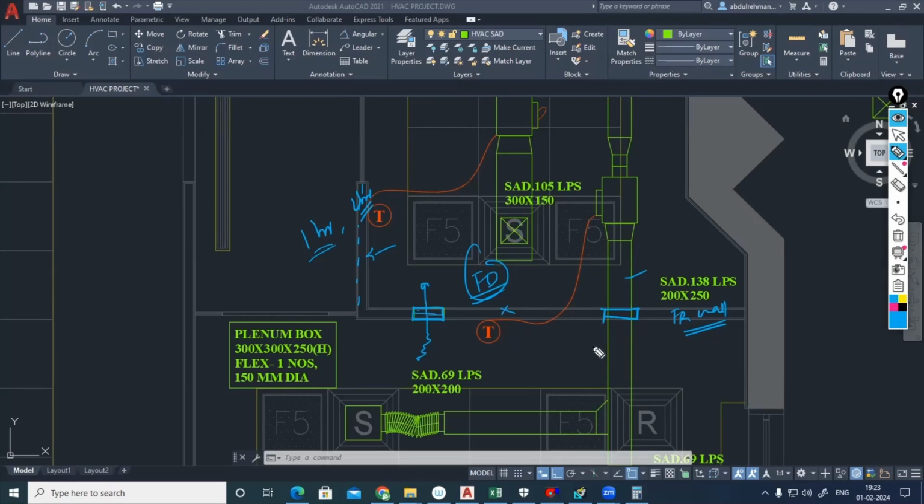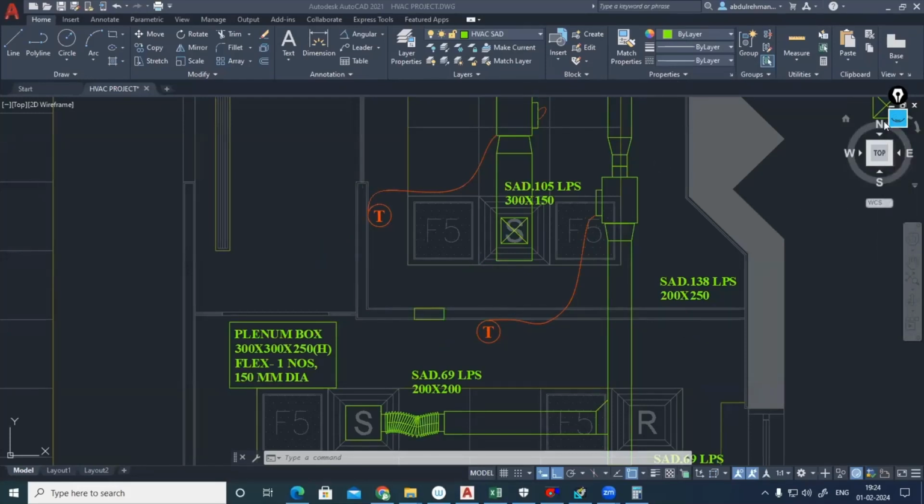But in case you are planning to propose a fire damper, then instead of a wall opening you have to provide a duct. The duct you can simply provide as a piece. The same function the wall opening is doing, this will also be doing. This will act as the path for return. This duct is called a TAD, transfer air duct. The function of a wall opening and the transfer air duct for this space is similar.